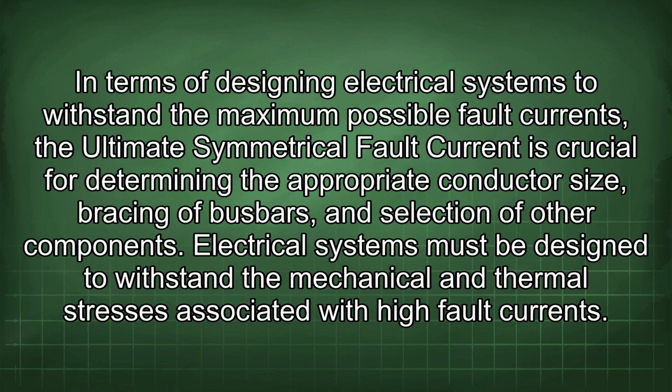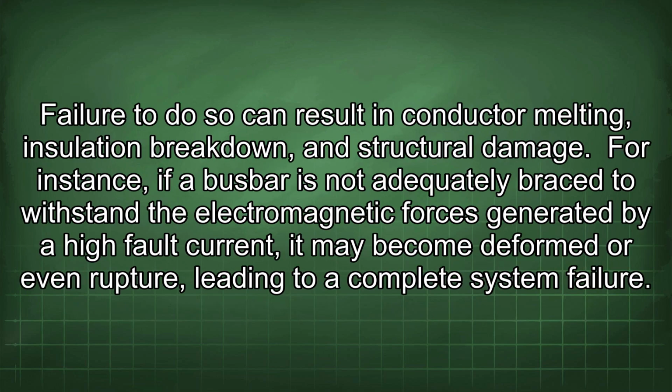In terms of designing electrical systems to withstand the maximum possible fault currents, the ultimate symmetrical fault current is crucial for determining the appropriate conductor size, bracing of busbars, and selection of other components. Electrical systems must be designed to withstand the mechanical and thermal stresses associated with high fault currents. Failure to do so can result in conductor melting, insulation breakdown, and structural damage.